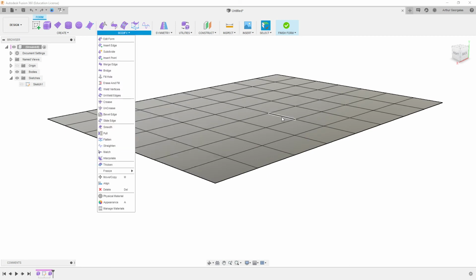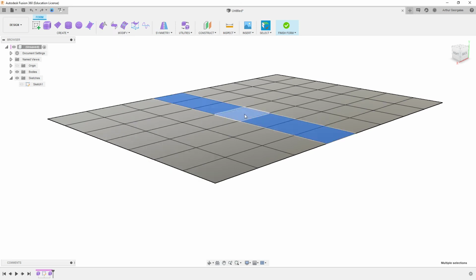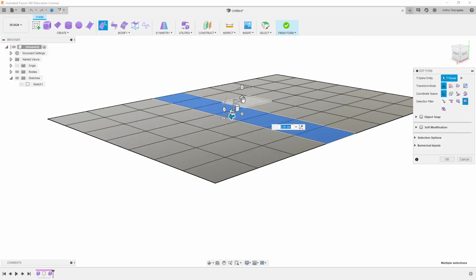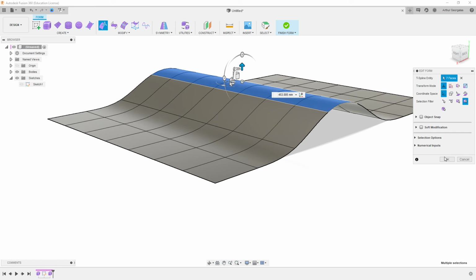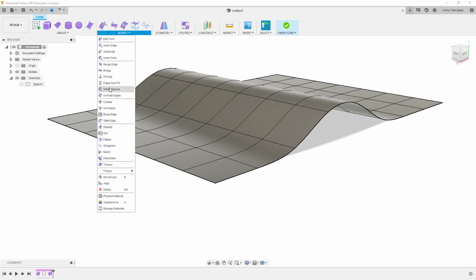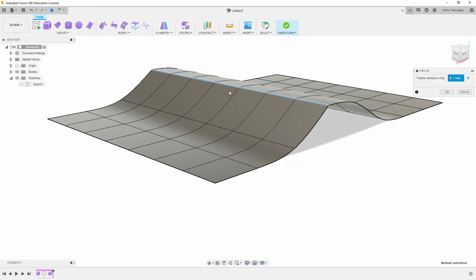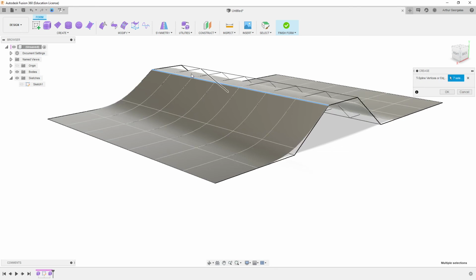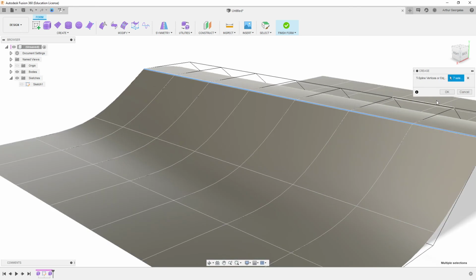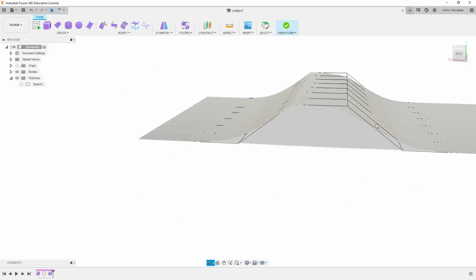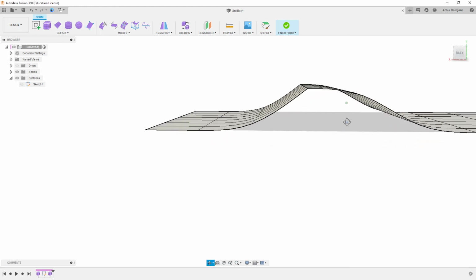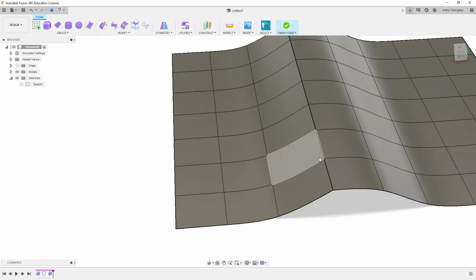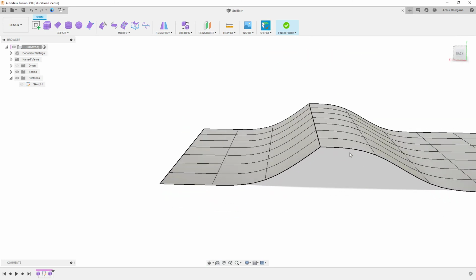Then we get back into crease and uncrease, super useful commands. So again, just to show we've got that, and if we come through with crease, what it's going to do is pull it up to where it actually matches that box shaped line. And I can't stress enough how important it is to use the crease command to create the geometry first and then start to smooth things out around it.